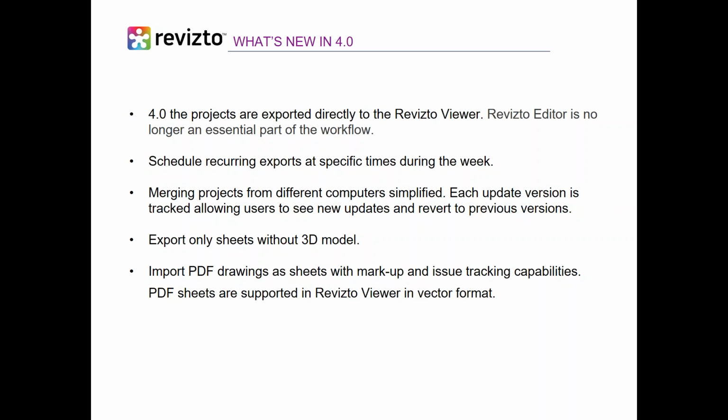It really does simplify that, as opposed to the user having to launch the export of the model. They can actually schedule it in. So if there's a regular design review meeting coming up on Monday, they can schedule the update from the design tools, from Revit into the Revizto environment, to happen Friday nights. And so it's there ready to go Monday morning when everybody gets started in that design meeting.